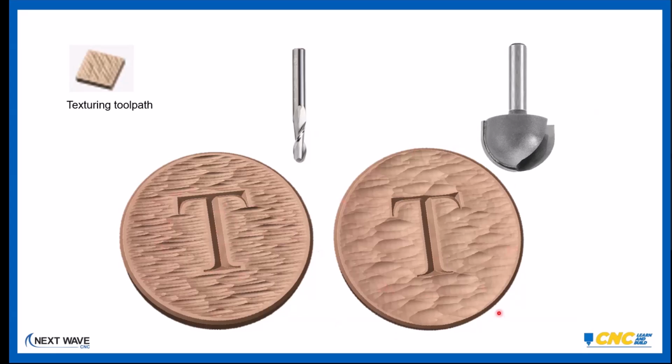In this side over here, I've used a larger ball nose bit. And this one, if you look closely, you can see I didn't have the offset quite wide enough. You can see how right here at the bottom of the T, it gouged the bottom of the T. It gouged a little here at the top. So in this one, I really needed a little larger offset to give me a little more area around there. But it's a fun one to play with.